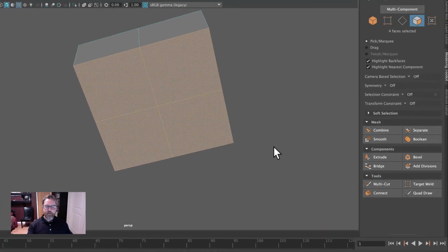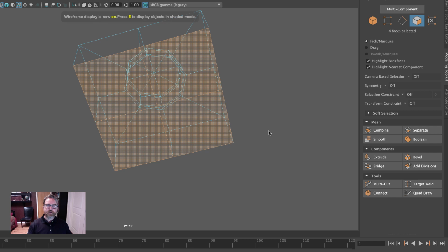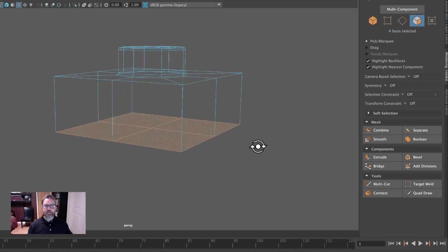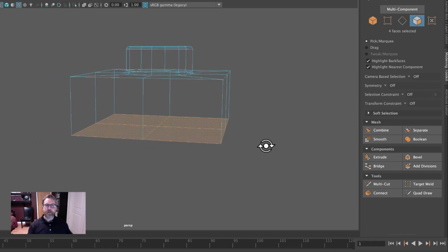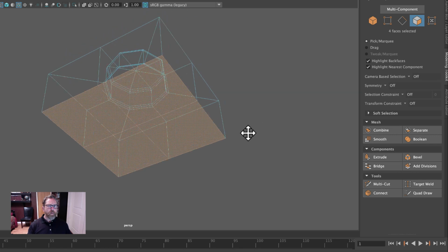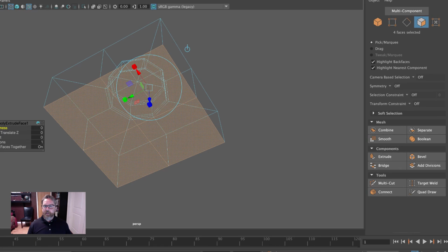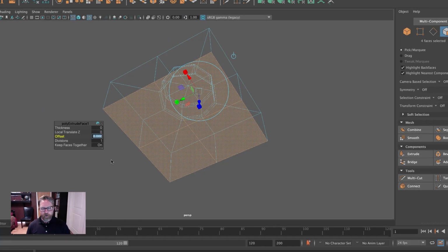And you'll recall that anytime you're making face selections, it's a good idea to hit the 4 key just to make sure you've got a clean selection. You didn't accidentally select something on the other side. If I had, I could hold down the control key and draw a bounding box around what I wanted to deselect. All right, with those 4 bottom faces selected, we'll hit extrude, and the offset, as you'll recall, is 0.8, and so that gives us our recess here.